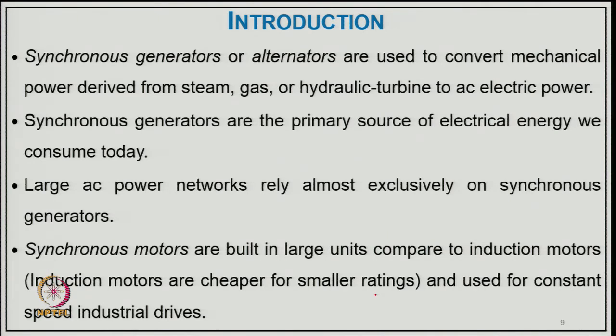Synchronous generators, also called alternators as they produce alternating current output, are used to convert mechanical power derived from steam, gas or hydraulic turbines to AC power. Synchronous generators are the primary source of the electrical energy we consume today, and large AC power networks rely almost exclusively on synchronous generators. Synchronous motors are built in large units compared to induction motors. Induction motors are cheaper for small ratings and are used for constant speed industrial drives.